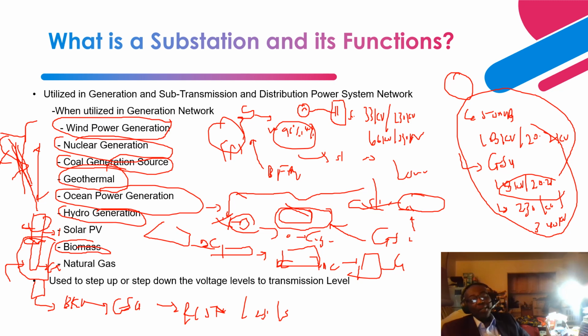The boiler boils those trash elements and the trees that have been broken down into several pieces. Water is fed through the walls of the boiler, gains heat energy from the boiler, and is converted into steam.